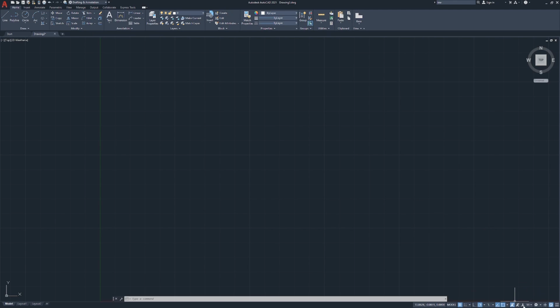These are your annotation buttons down here. We're not going to talk about them right now. Next button over to the left is your 2D cursor for your snaps. We'll discuss that later when we're actually drawing things. Just know that it's there. Also, F3. So function 3, you'll notice that the light turns off. Because it's off, it's going to tell you down in your command line, your O snaps are off. O snap, object snap. If I come back over to the O snap button down here, you can also turn it on by just clicking it. F3 is faster.